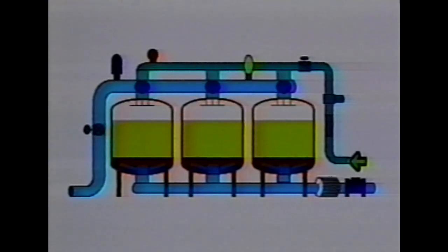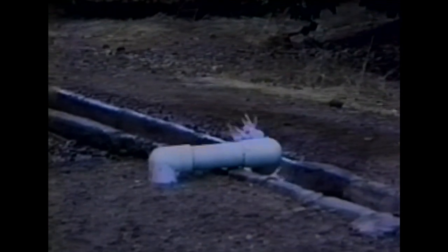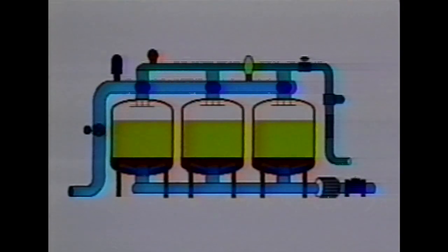It is essential that the operator be able to take samples of the backflush water during the initial adjustment of the backflush flow control valve. That means the end of the pipe must be accessible. The flow control valve should be adjusted so that there is just a little bit of media leaving with the backflush water. By holding a screen under the open pipe discharge, one can see if sand is in the water.